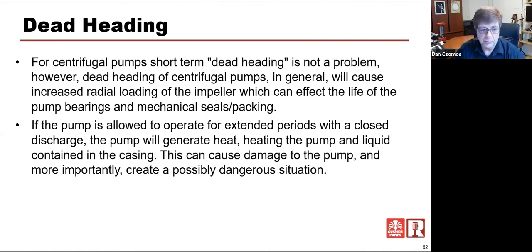It may have some blockage somewhere, but at zero flow, blockage and friction loss are basically thrown out the window because they don't exist. Friction loss doesn't exist at zero flow. So a deadhead test can be really helpful for you.